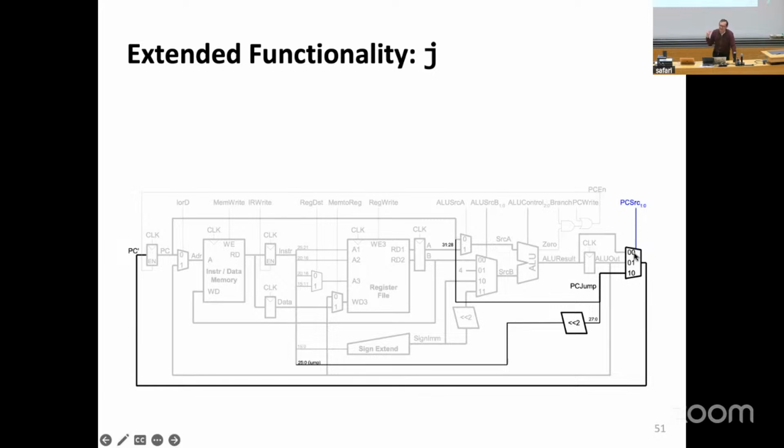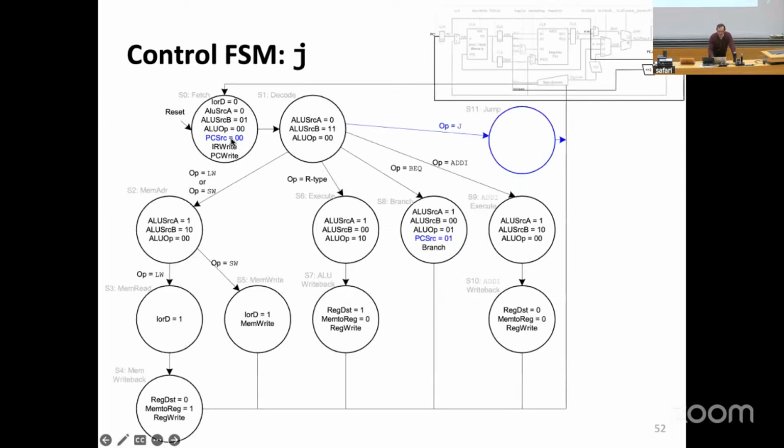We did this actually in the single cycle processor as well. But if you want to add instructions, you essentially need to add data path elements and potentially also new control signals. And then you actually need to change the control signals that you've done over here. So if you forgot an instruction, for example, no worries. You just need to add the data path elements, add the control signals, and make sure all of those control signals are updated in all of your states accordingly so that you do the right thing. So that's one of the other beauties of this machine, in the sense that you can easily modify things. This sort of structure, finite state machine, enables you to modify things easily.